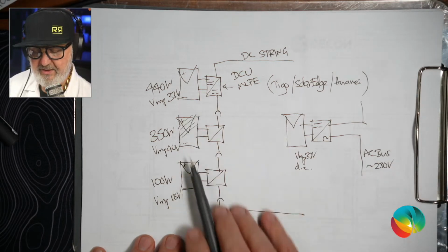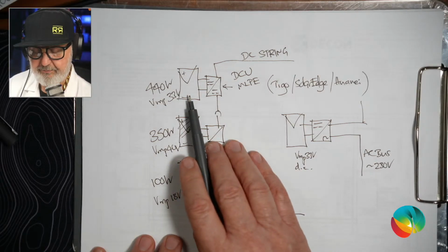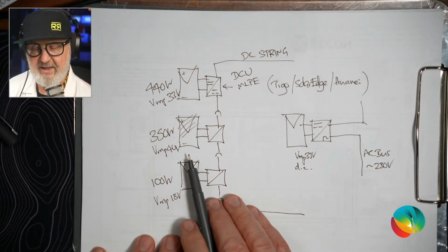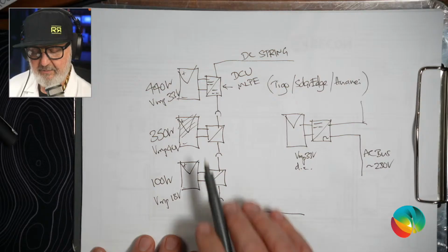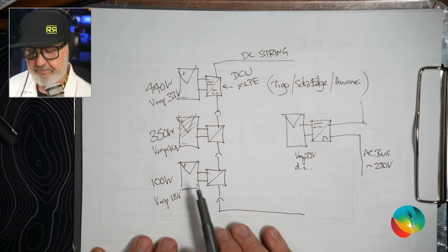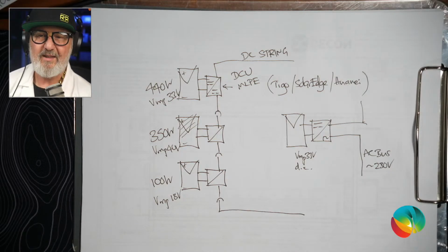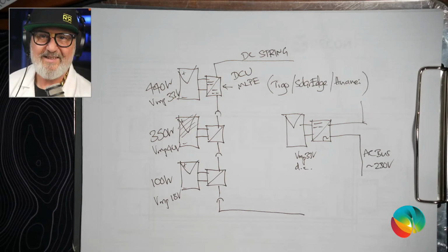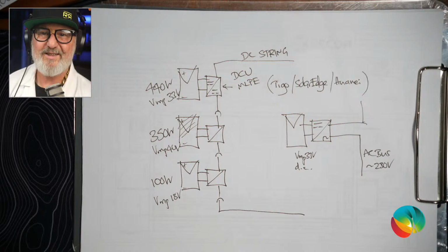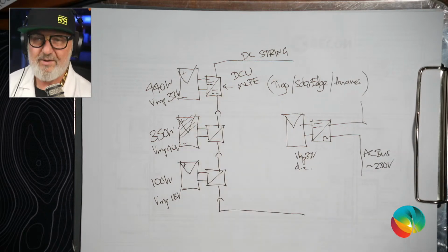So it gives you pretty much the same advantages. It means that each module is working as best it can, shade tolerance, mismatch of modules, not a problem. And so for installations that have difficult location requirements, like a chimney in front of some of your panels, Charles, that's when one of these two solutions can come to the fore.